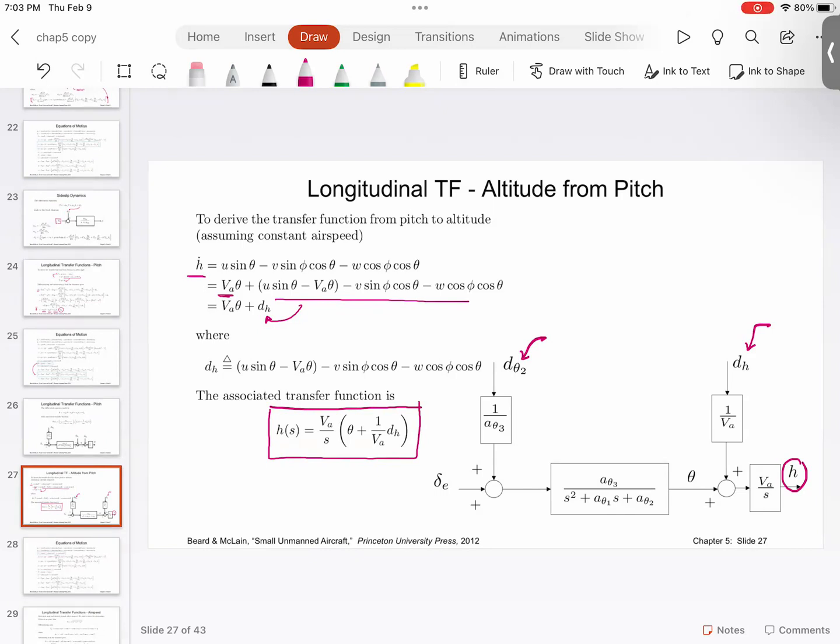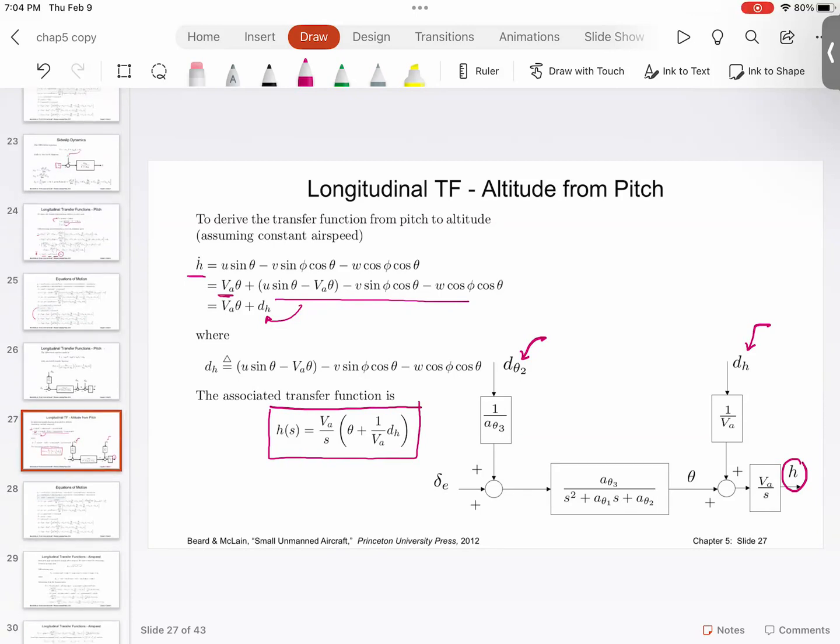Sometimes I get hardcore controls engineers saying, no, this system is not good, this system will not work. So if you work in nonlinear controls, which I do, my recommendation to you is, as a comparison, it's very simple to implement in MATLAB or anywhere. Just compare the performance of your nonlinear system with these types of linear transfer function techniques, or some simple approximation linear techniques. Many a times, based on my experience, 70 to 75% of the time, the linear technique would work just fine, and that is easier to implement. So just try that.